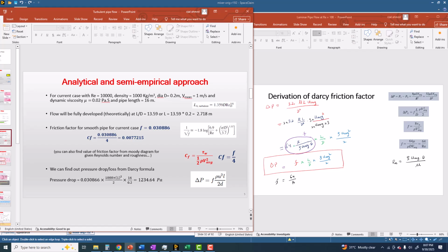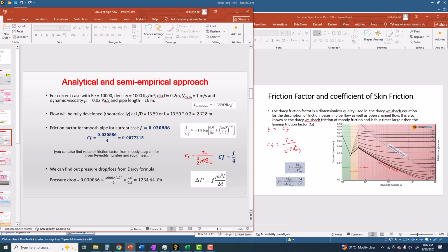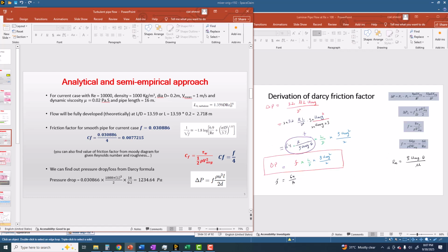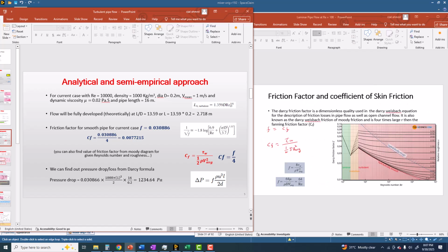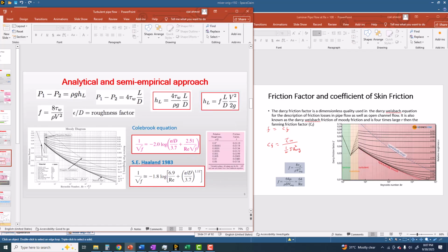But what we tend to use in turbulent flow is that the velocity profile is very simple in the case of laminar flow, but in turbulent flow the velocity profile is slightly complicated. It depends on many things, on the turbulence as well. So we don't put in these factors directly, but instead we put in the equations. For example, because we know the velocity profile in laminar flow, we put their values there, take the derivative for the wall shear stress, and we end up with the simple formulas. But here I will rather be using the formulas in this form.